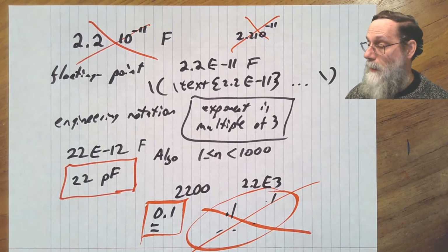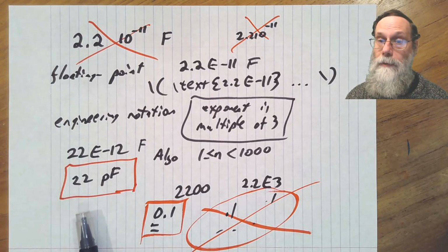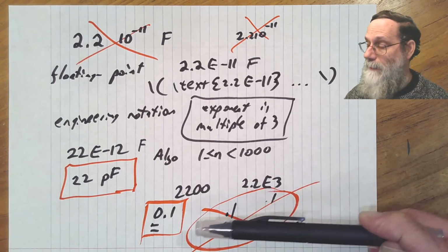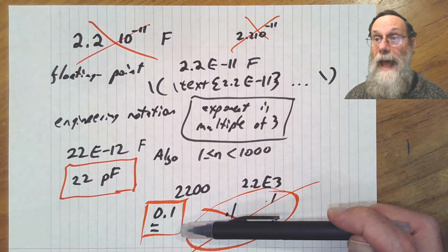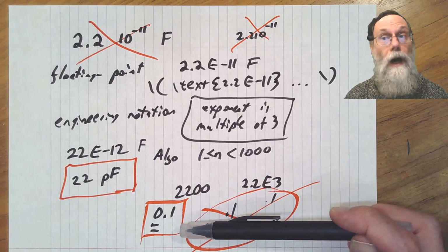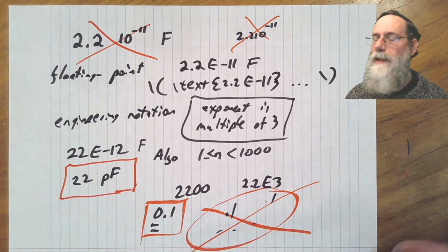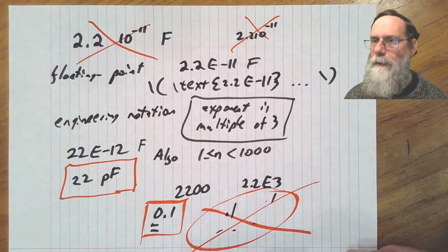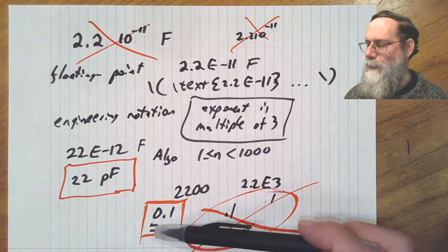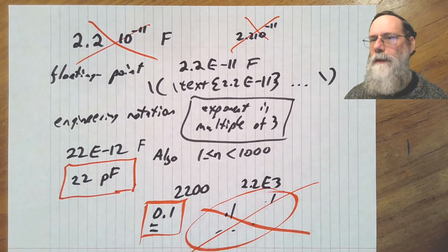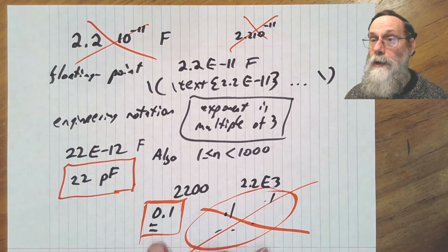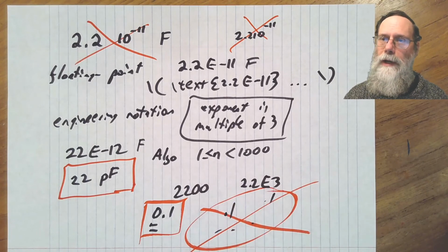And one of the nice things about using engineering notation and metric prefixes with this constraint that you're putting that number out there between 1 and 1,000 is that you never have to deal with leading zeros because you don't have any. You've always got, oh, if I want 0.1 volts, I'll write it as 100 millivolts. Occasionally, because you're doing a lot of stuff in volts and you've got one number that's just a little below 1, and you want to say, okay, I'll do this one still in volts, then you'll do 0.1 so as not to have to switch to millivolts for just one number in a table or something like that. But when you can, keep your numbers between 1 and 1,000.